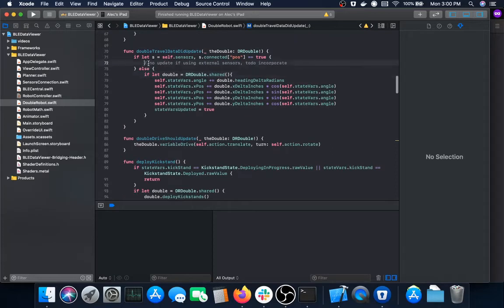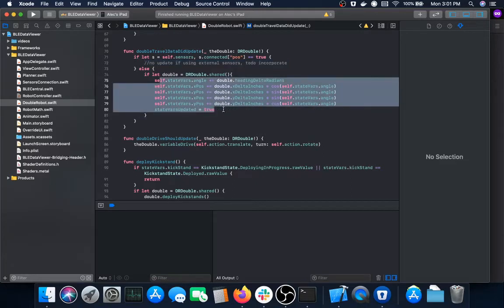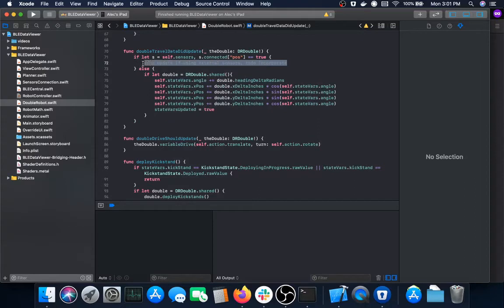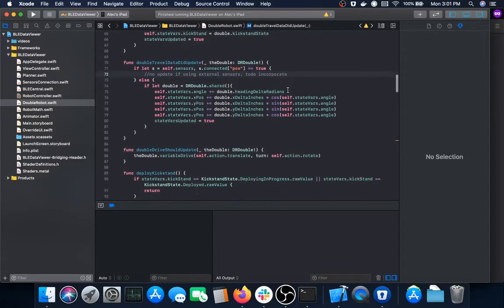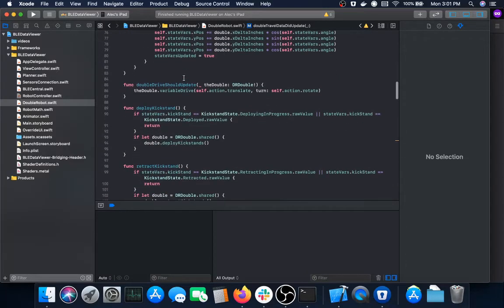In the future, we could process and calculate those encoder updates and send that back to the Linux computer to incorporate into the state estimate for the RealSense camera package, because the RealSense camera allows you to input encoder values and get an even more accurate state measurement. So that's where we would do something like that.